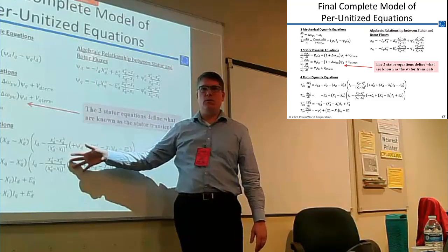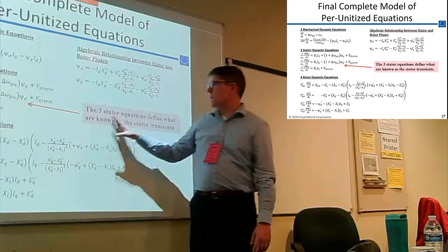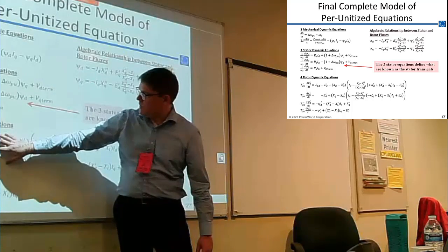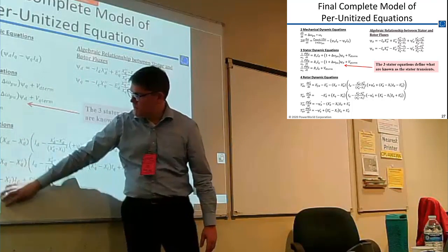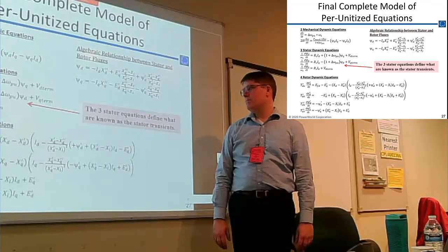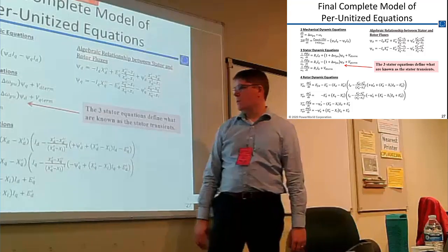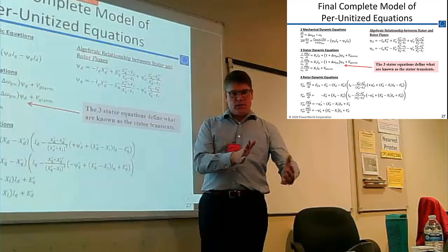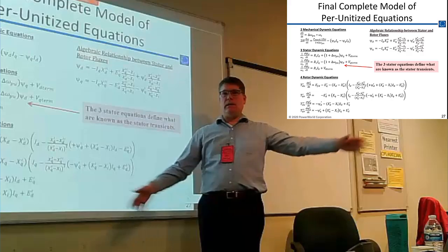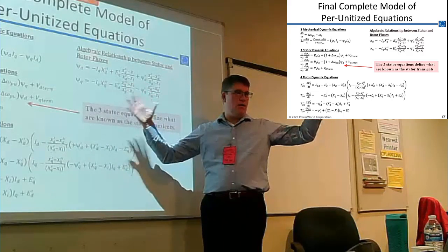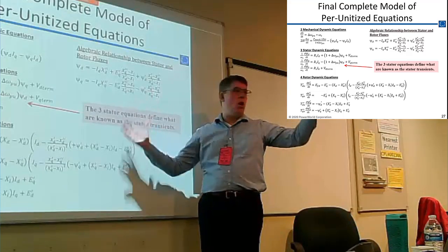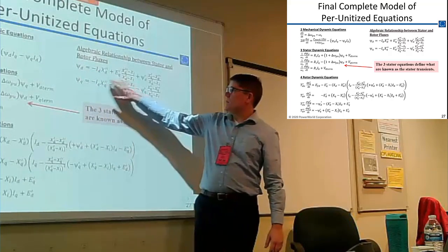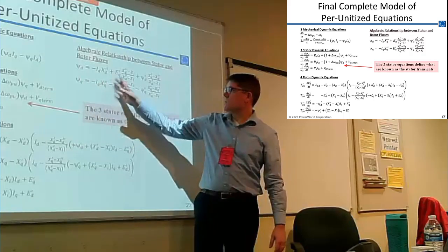The only difference is down here, the equations up here. There's 4 different fluxes on the rotor, and we're assuming that all the flux on the rotor eventually comes over to the stator and comes back. It's not like leaking out and disappearing somewhere, because again, the conservative coupling field assumes there's no loss in this transformation. So these fluxes up here are just the flux on the stator. So it's the relationship between the stator flux and the rotor fluxes.